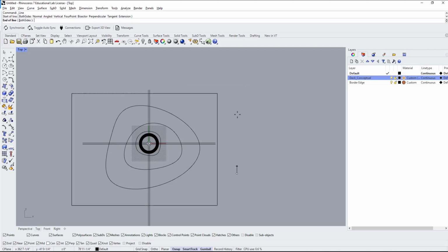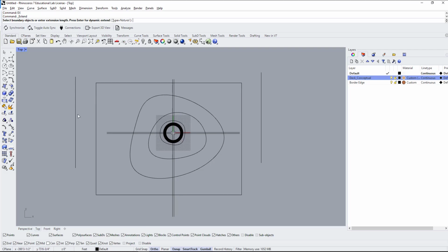Now, one way I always create my curved roads that kind of project onto my surfaces or the side is I do some form of excavation. So the way I do that is I copy my surface for the base and then keep that in a different layer and then trim that with my reference lines. That way I only model my landform once. So you'll find that more in the link in the description.